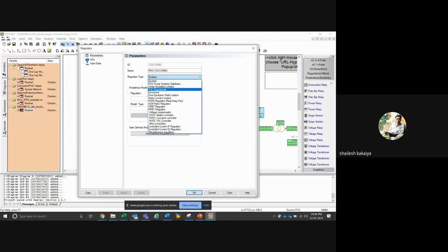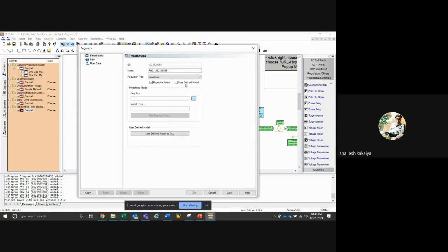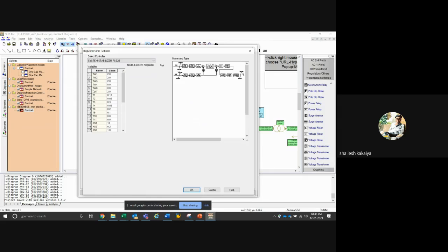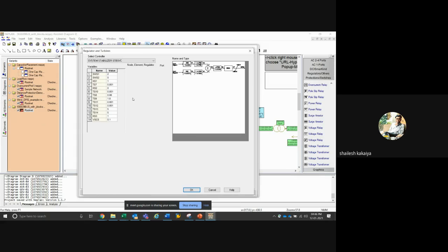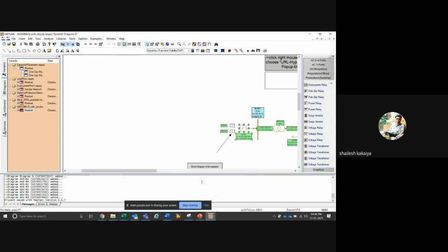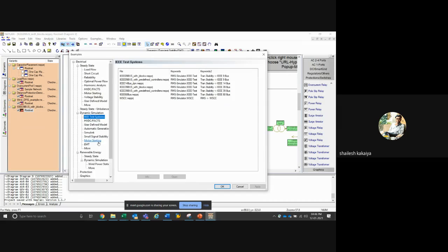So then next I have some governors. Similarly, the governor types are built in, and then I have power system stabilizers. So there are certain power system stabilizer models also as per the standards that are built in, along with the relevant default data and the control diagrams. So the biggest advantage is that you have a huge amount of dynamic library already included within this. In addition to that, NEPLAN has a Simulink sort of a mechanism where you can make your customized control diagrams as well. So similar to MATLAB or Simulink, you can make customized systems.